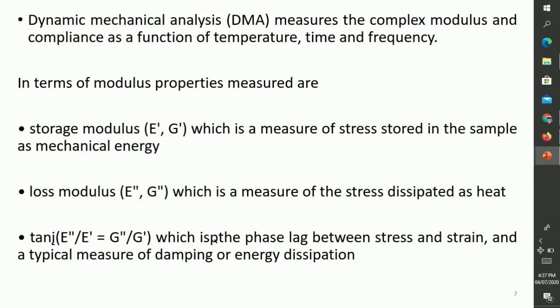We know that DSC is helpful to measure heat flow into a material, the endothermic process, or out of the material, the exothermic process, while thermoset cure is exothermic. DSC includes the measurement of different transitions, conversion alpha, the reaction rate, and the heat capacity.